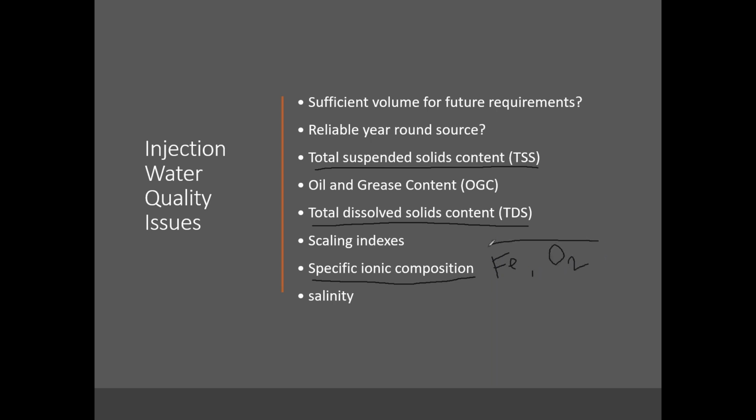These are two important elements that should be removed before injecting the water into the formation, and the salinity. Oil and grease content is another thing. This particular part comes when you are doing remediation work for produced water re-injection, then this oil and grease content should be taken care of.